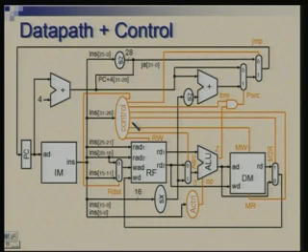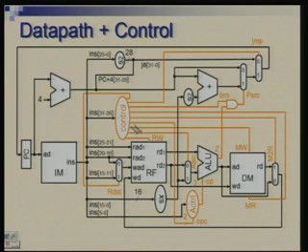So, we will have some information coming out from here connecting to this, and this needs to be just 2-bit information, because we like to distinguish between 3 different cases. The R class instruction, add, subtract, and, or, and SLT, that is one possibility. Load store together grouped as another possibility, and all the rest as third possibility. So, we will take 2 bits out of this and connect to this, and I am calling it OPC, which stands for operation class.